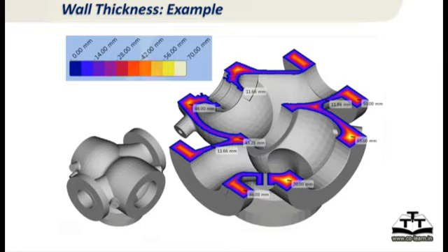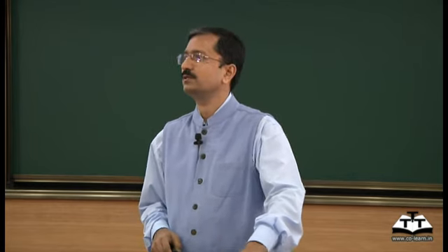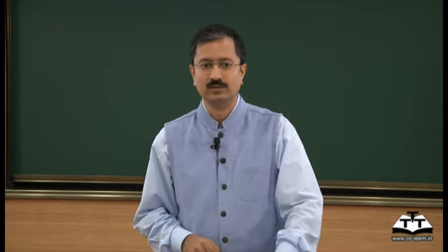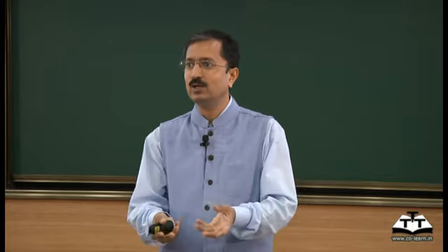Now with that definition, for the same part, if you compute the values of thickness, the picture will look like this. So you see now, the values can be actually measured at different places. You can see somewhere the thickest section is 70 millimeters, somewhere the thin section is I think 43 millimeters, 46, 11 millimeters somewhere, the blue line. So red is thick, blue is thin. These are not temperature, these are thickness values colored so that you can visualize it nicely. So it's possible to visualize thicknesses now in a complicated casting like this without doing hand calculation of all the circles. You can write a program for doing that.